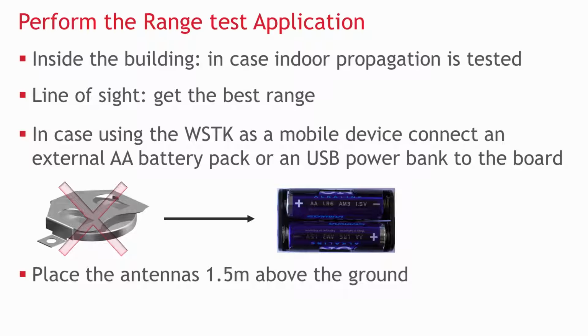Please note, if you are going to use the WSDK as a mobile device to run the range test, it is recommended to connect an external AA battery pack to the WSDK board. The coin cell battery will not have enough power to do long-term testing.